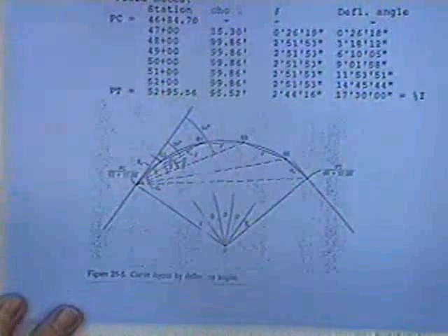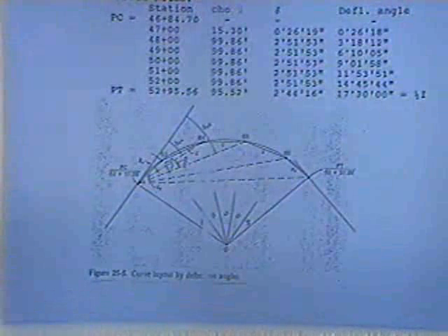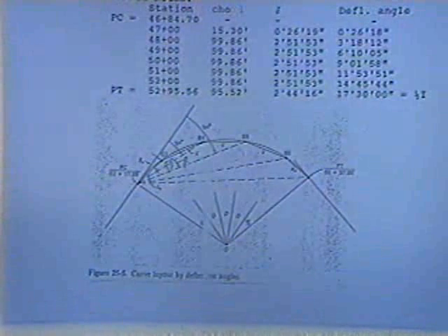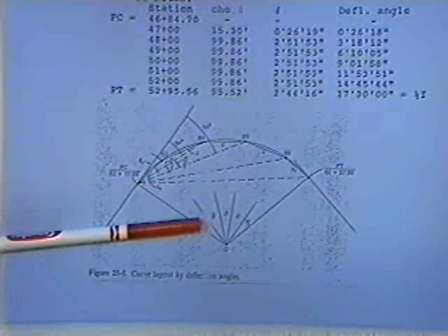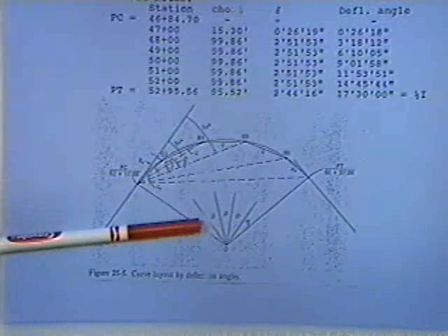And then just to give you a picture of what that would look like, there's the following page that talks about vertical curve layout by deflection angle methods. If I could get the overhead there in your notes. This is just simply the calculations for that particular problem, illustrating the process that we just went through. And you'll notice there in that slide, down in the bottom, you see these degrees of curvature, and those are the angles that are subtended by a 100-foot arc in this particular definition.